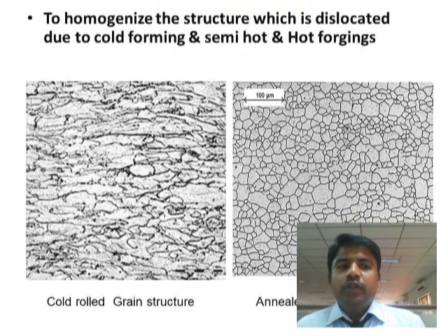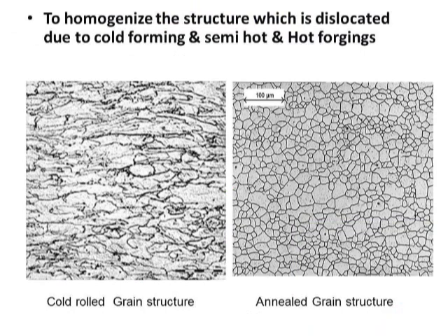So this is it. You can see the grain structures for cold rolling. You can see irregular structures. After annealing, the structures are arranged into defined and very closely bonded strong structures. This we call the recrystallization annealing process, for treatment after cold rolling or a press process. You can go for recrystallization annealing. I can show the next slide now.